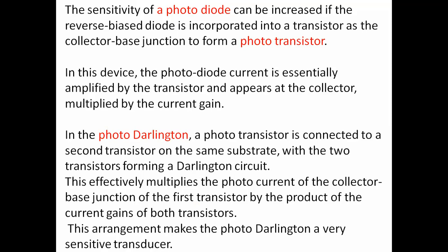We will use these transducers for measurement of different physical variables, such as displacement. We can use the strain, surface strain, and also we can use it for the pressure. If we consider the active transducers, active transducers are based on the electromagnetic induction principle, such as electromagnetic transducers, thermoelectric transducers, that is thermocouple.